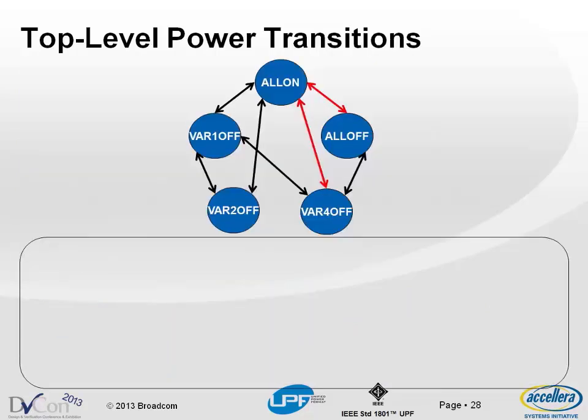We spoke about power states. What about transitions? How do we go from one state to another? Is it legal to go from all states? And for this, again, you need to build a system-level state diagram or state bubble. So you tell what are valid and what are invalid combinations. It's always easier to start off with the invalid combinations first. You just rule out that anything going from this state to this state is illegal. And you do that with a command called describe state transition.